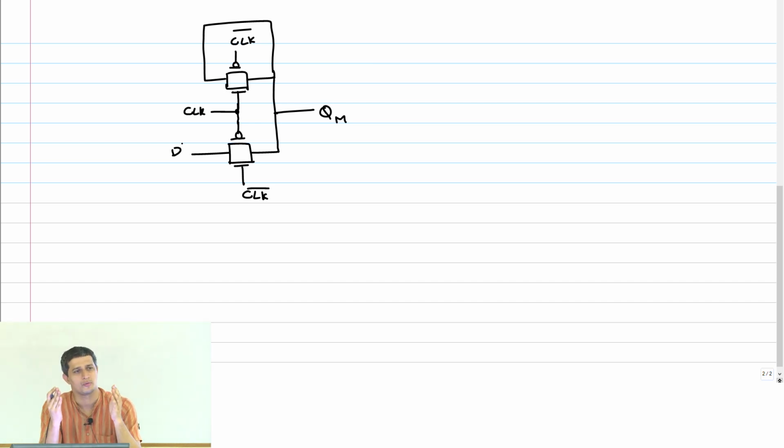What does characterization mean? It means that as a standard cell designer, I design a gate or a flop, and then in your assignment now, you are characterizing the delay of an adder against the loads, against the slew. You're basically saying if the load is this much and the delay is this number, I should be able to give you that number. That is what is known as characterization.